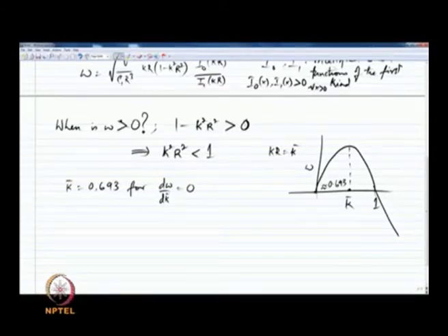So, this k bar being 0.693 tells us the wavelength associated with the disturbance that is likely to grow the fastest. And again, one of those remarkable coincidences of linear instability analysis when compared to experimental observations is that this particular wavelength has been observed in very simple faucet breakup, liquid jet breakup experiments, let us say from a bathroom faucet. The drops formed from a simple cylindrical jet breakup experiment agree very well, as a matter of fact, with this prediction from linear instability theory. It was one of the early successes of linear instability analysis that has led to their widespread use in many different systems thereafter.